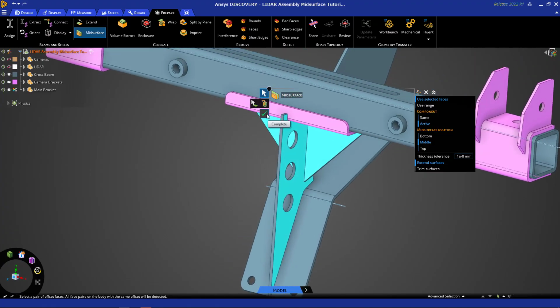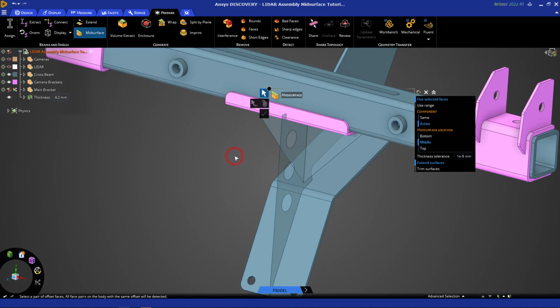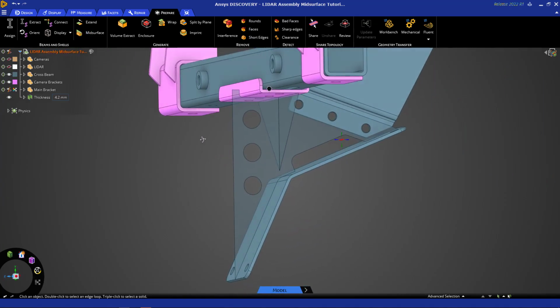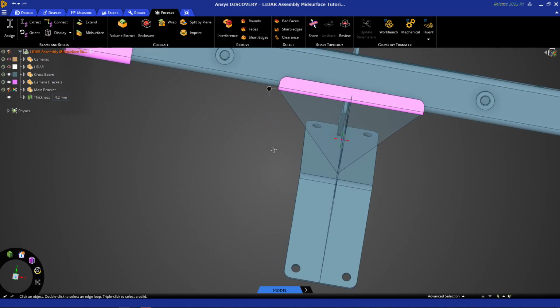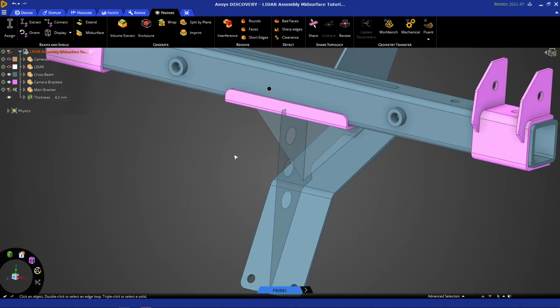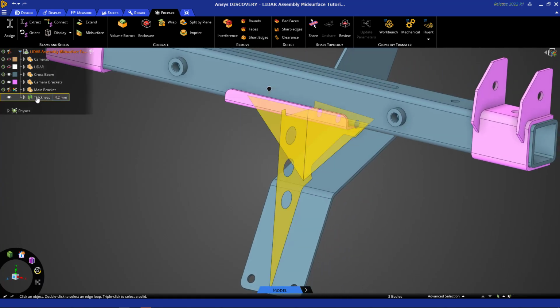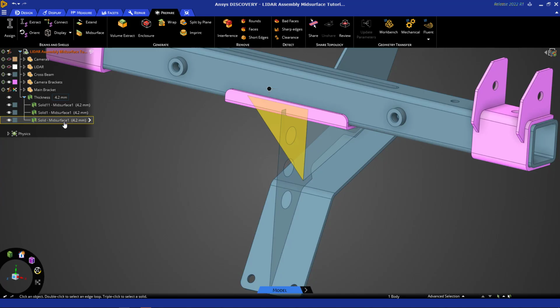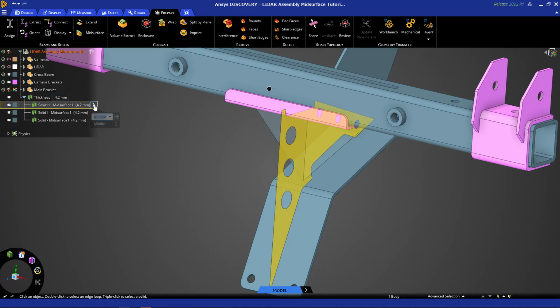Let me click on complete, so we'll be able to look at what's been created. Here we see that for our selections, we have the right mid-surfaces created, and these are housed in our overall geometry tree right here. If you look at this component right here, we can see all the different mid-surfaces attached here. We can click on this arrow and then update the thickness that you want for the part. It can be different for each of these, or you could change it right here, which will change the thickness for all the parts in that component of mid-surfaces.